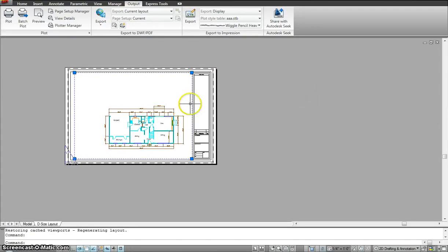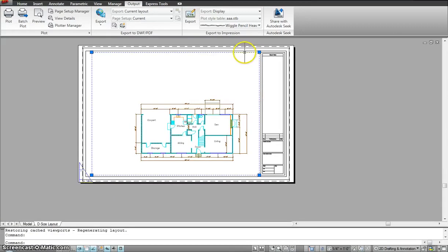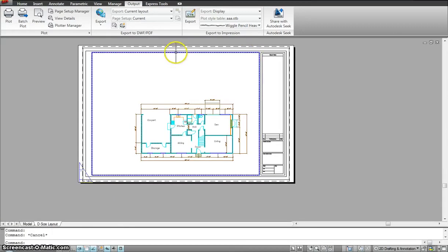Now what I would be doing is trying to explain to you this viewport. Now the viewport, as I said, is a window that shows your drawing underneath. So right now I am in my paper space. If I wanted to jump to my model space from here, instead of clicking right there, I can just double click onto my screen. Now you see this viewport gets highlighted. What that means is I have currently gone through the portal to my model space.